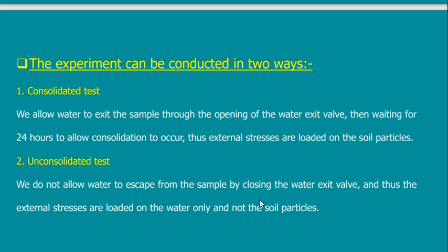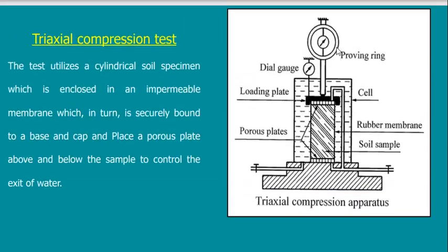For an unconsolidated test, I will keep this closed. We do not allow water to escape the sample by closing the water exit valve, and thus the external stresses are loaded on the water only, not on the soil particles. We said that if water is not allowed to leave from the beginning, then all the additional forces will go to the water. So I'm trying to resemble in the lab the real conditions of the soil inside.